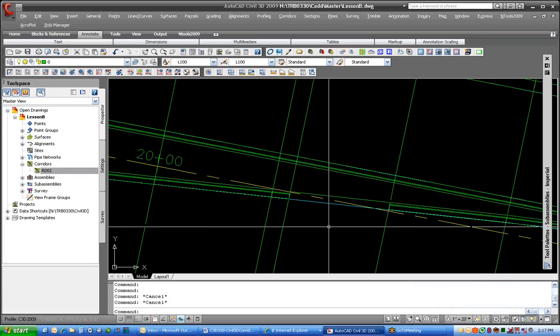So, all right. Any other comments or questions? Good eye there, Michael. And did I see correctly that looking at that, when we looked at it in sections, if you tell it go minus 2% on the right side, it doesn't switch it to a positive 2% when it crosses? No, because everything's relative to that link location. So we said go negative down away from center line. So even when I pull it to the other side, it's still going away from that center line point. So that's why it stayed negative.